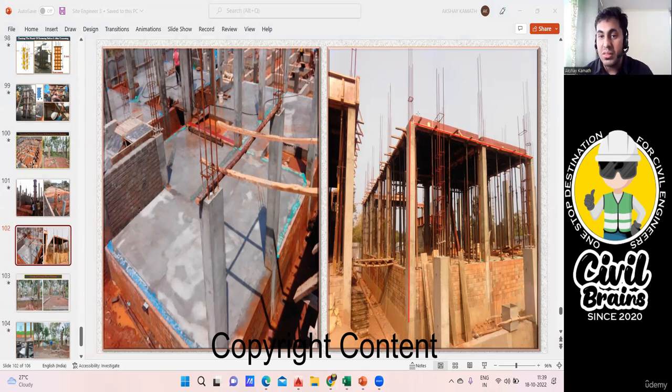And finally, you do a slab, you do a beam shuttering. And this is your final height. Your concrete will come up to this level. This is the actual height of your column. But in calculation, I'll take the complete height. In calculation, I'll say from the top of my plinth beam to the top of my slab concrete, this is my floor to floor height, which is 3.3 meter. I'll take 3.3 meter. Okay, not an issue. You can do it that way.